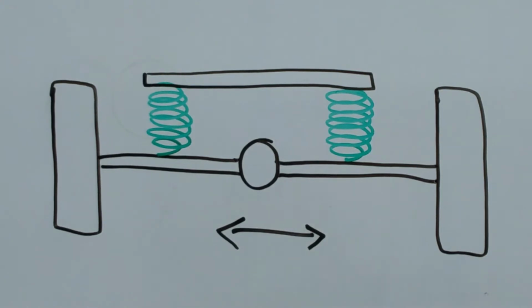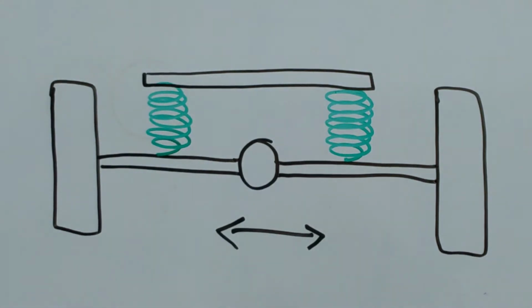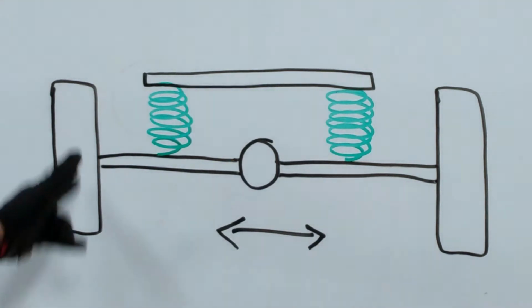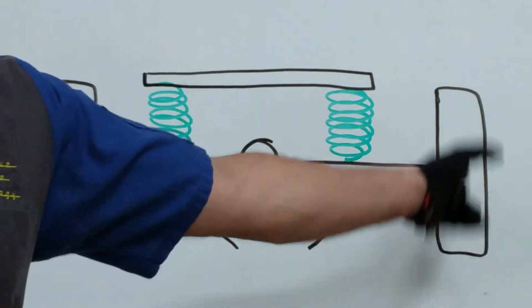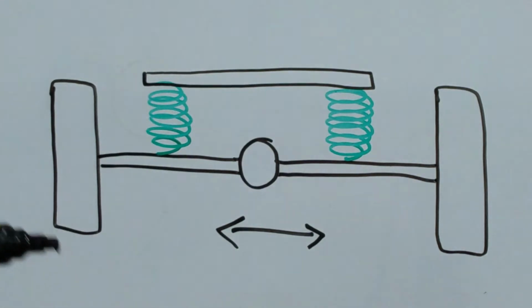So the popular method for controlling the movement side to side of the axle. For example, when looking at vehicle specifications, there's a couple dimensions that are mentioned through the manufacturer's engineering points. One of them is track width. Track width is the distance from one hub flange to the center of another hub flange across the width of the vehicle. The wheelbase is from the center of the axle from the rear to the center of the axle in the front. Track width is side to side.